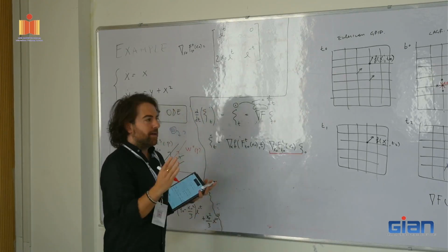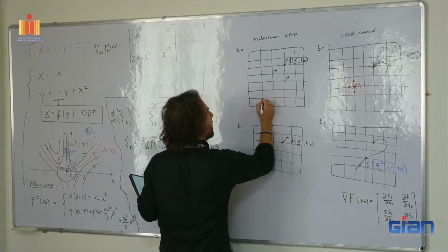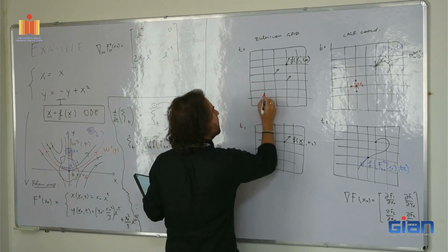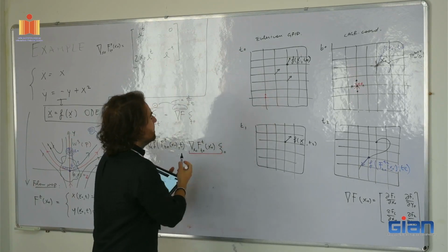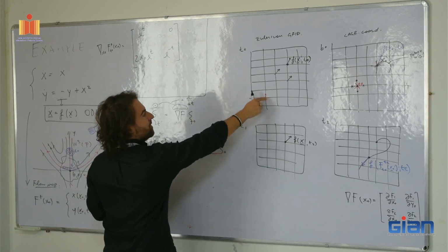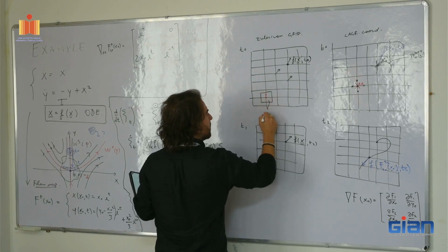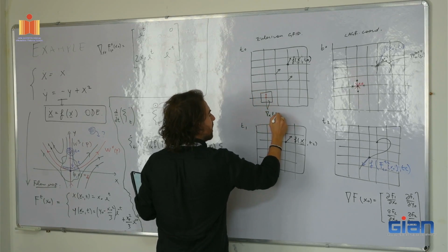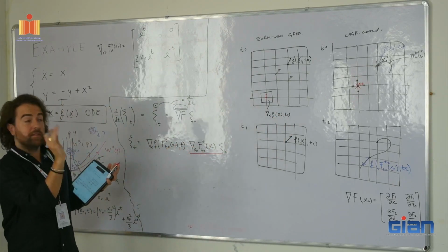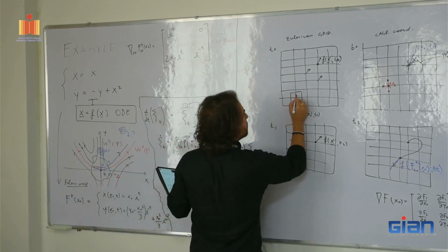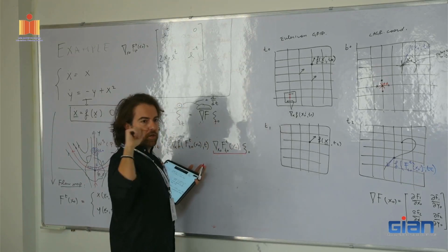Let me give a very practical example. Let me actually pick another data point. Let's say I'm here. This is my x0, and now I start along this direction. So the only thing that is going to affect the dynamics of zeta 0 is the velocity gradient here. There is going to be a particular dx f at this particular x0, t0. And this tells me that I'm going to start feeling some sort of shear. Let's say that the flow does like that. So zeta t dot is going to be in this direction at the initial time.